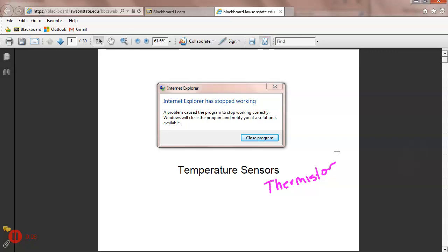We have two types. We have what? NTCs, which is the one we looked at, and we have PTCs. And what's an NTC and a PTC? Coefficient, right? So an NTC, its resistance goes down with temperature. And PTC, its resistance would go up. And the only one that we've got around here is an NTC. And what was the other one, Jose, you said?